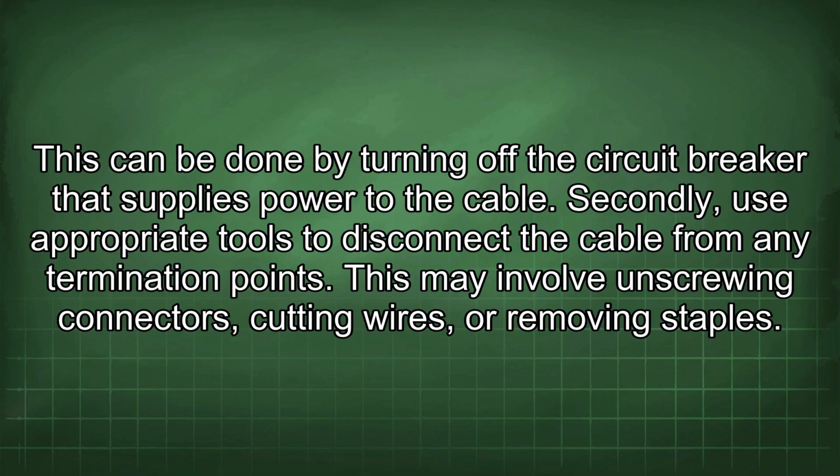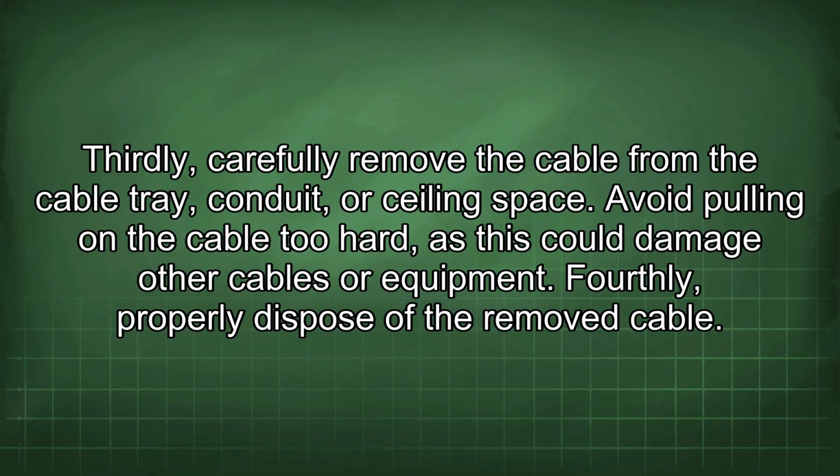Secondly, use appropriate tools to disconnect the cable from any termination points. This may involve unscrewing connectors, cutting wires, or removing staples. Thirdly, carefully remove the cable from the cable tray, conduit, or ceiling space. Avoid pulling on the cable too hard, as this could damage other cables or equipment.